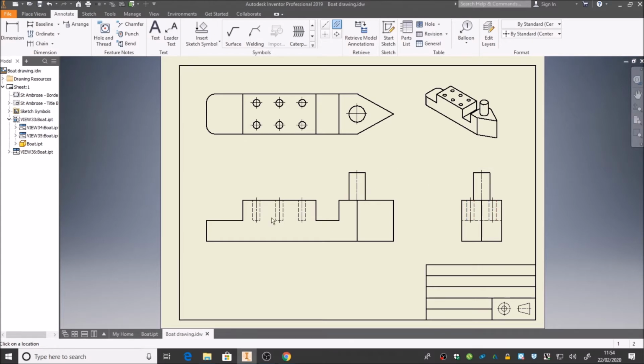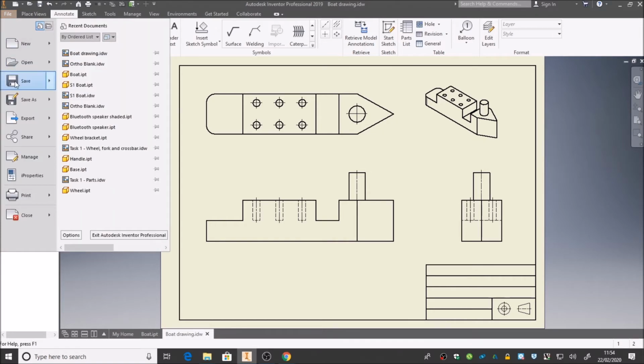And once we're finished putting our centre lines and our centre marks in, we go right click and, oh, create's not available for us, we must be finished. Let's go right click and escape then. Okay, and at this point, save your work again. File, save.